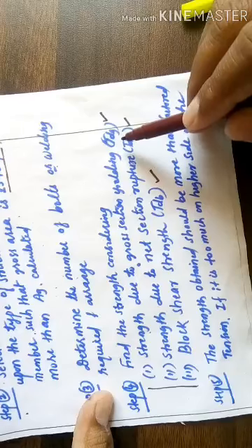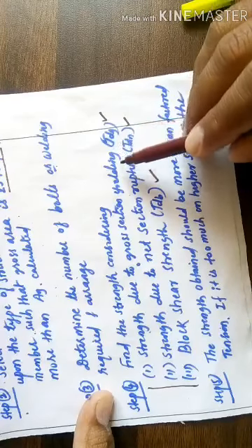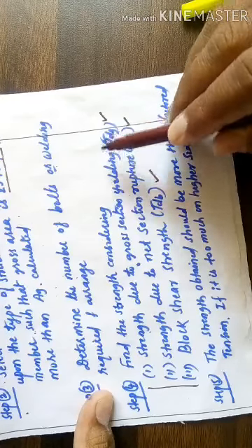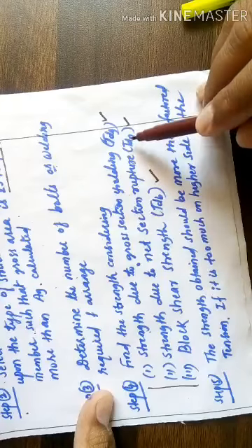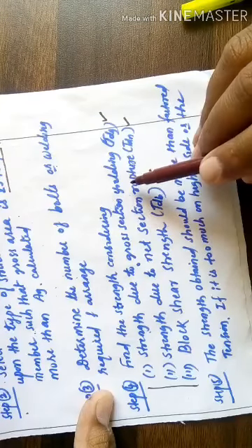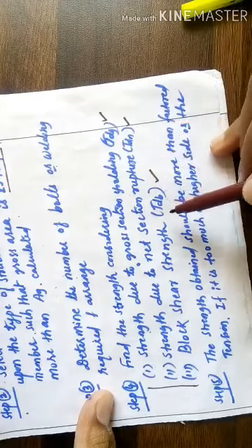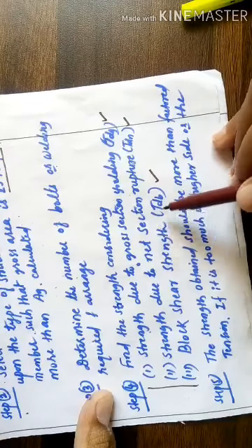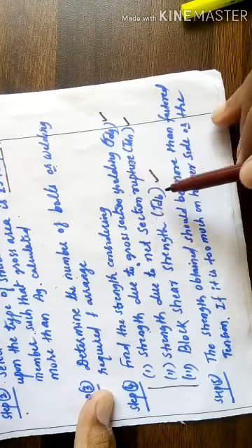If the assigned section gives Tdg more than the factored load, then it is safe. If in rupture it is more than the factored load given, then safe. Then Tdb also, if it comes out to be more than the given load, then it is safe.